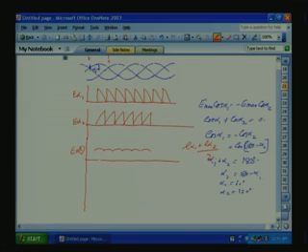Now, what is our ripple voltage for this question? The ripple voltage that is coming across the circulating inductance, which suppresses the circulating current, is ER. ER is equal to E alpha 1 minus E alpha 2. If you see here, it will be something like this. Here the average value will be 0. So the average voltage drop will be zero, and this ripple voltage will be dropped across the converter.